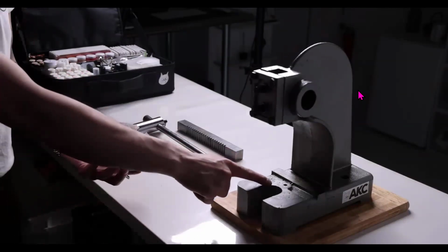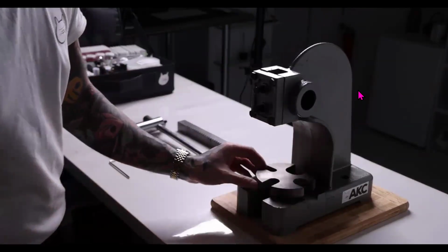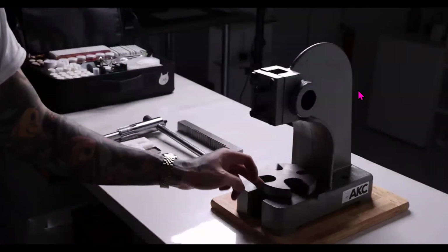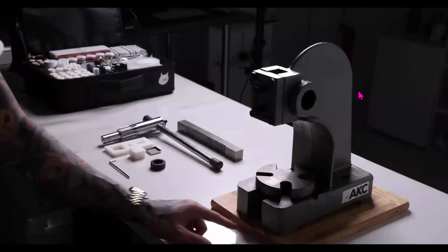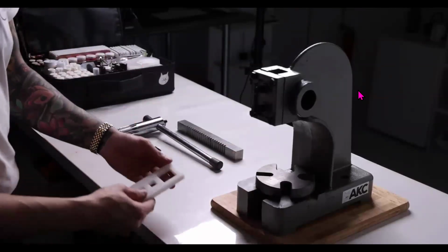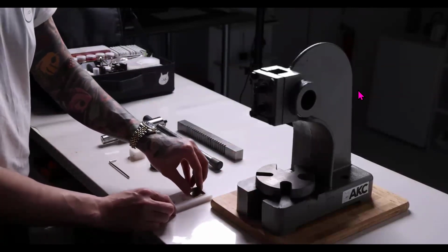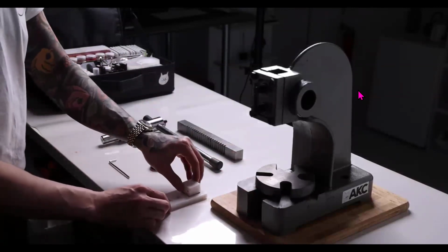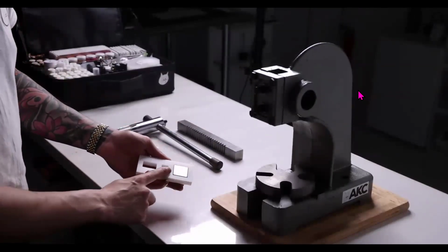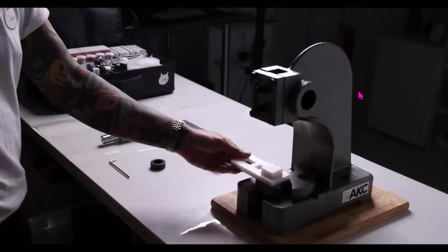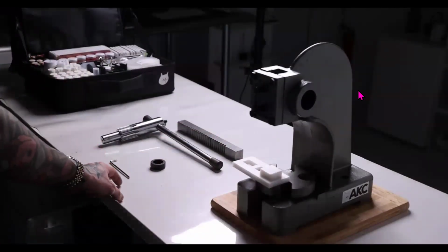So first, we're going to take the base piece and we're going to attach it to the ArborPress itself. You'll notice that you can spin this part around. Just pick the side with the widest surface. That way your mold can sit on top of it. Now we're going to set up the mold to use as a guide for the placement of the handle. Take your large pan, place it inside the mold, and use the large block and press it completely down. You want to turn it over to make sure that it's completely flat. Now place the mold on the ArborPress and make sure that it's resting on the surface and not the empty space in between.